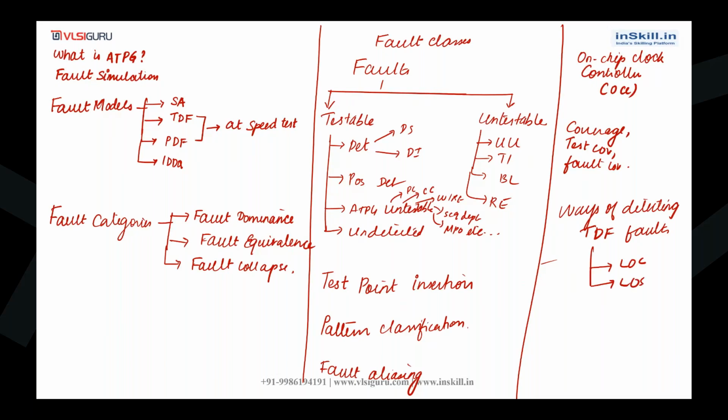LOC means launch on capture, LOS means launch on shift. What are these techniques? If you go for the LOS technique, then you need to enable the pipeline scan enable architecture. So we'll try to understand what the pipeline scan enable architecture is.